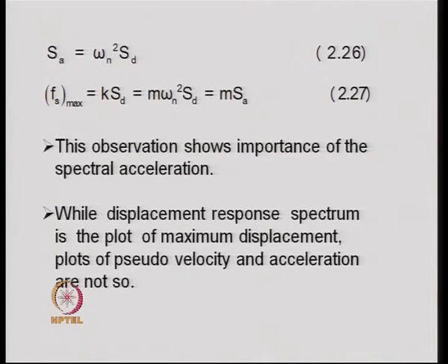Now, this observation shows the importance of the spectral acceleration. While the displacement response spectrum is the plot of maximum displacement, plots of pseudo velocity and acceleration spectrums are not so. That is, the pseudo velocity is not equal to the maximum velocity. The pseudo acceleration or spectral acceleration is also not the maximum relative acceleration.